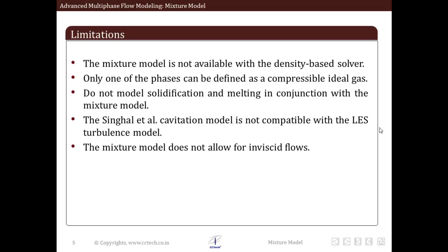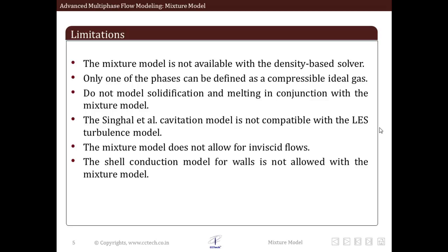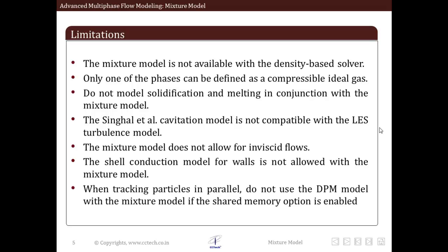The mixture model cannot be used for solving inviscid flows. The shell conduction model for heat transfer for walls cannot be used along with the mixture model. When we are tracking particles in parallel, we cannot use the DPM model with the mixture model if the shared memory option is enabled. So these are some of the limitations.